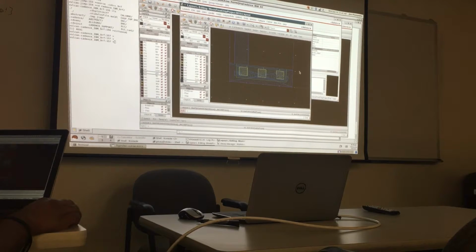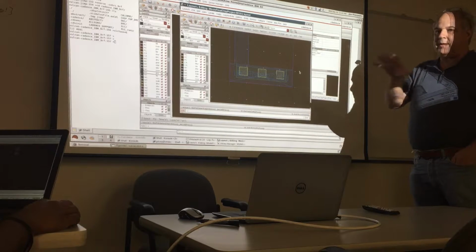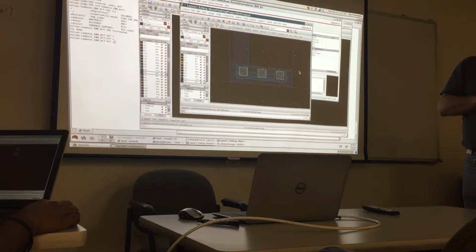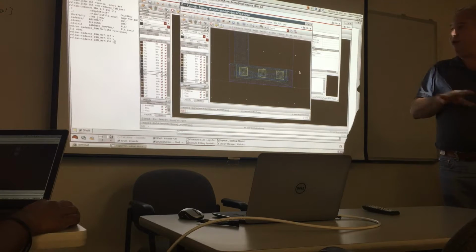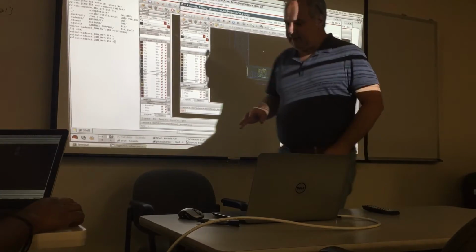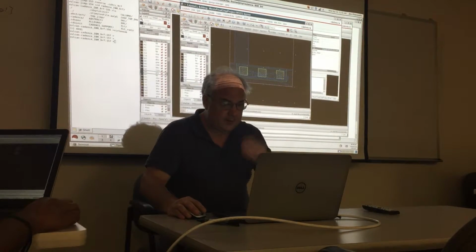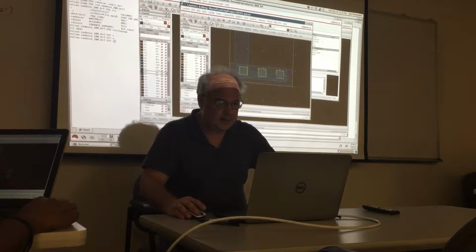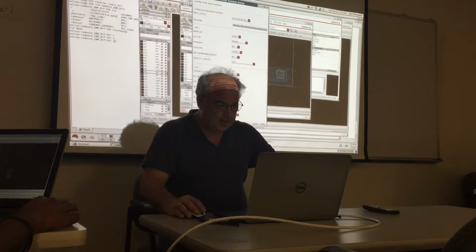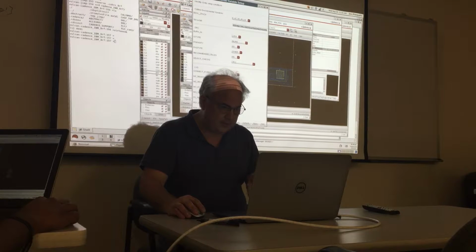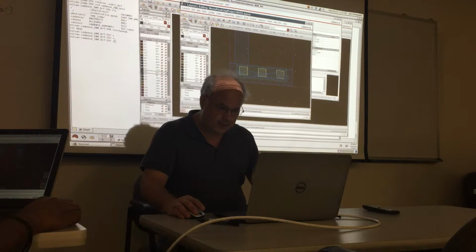Right, yeah, so bring up the inverter from the standard cell library because everyone should do this. I want everyone to get what's called a run set, for at least DRC and LVS. A run set is a set of parameters that you've tuned. So let's see, if I run DRC, this is a PDK menu that allows you to do various things. You just want to hit OK. For standard cell designs, it's already set up properly. So just click OK on it. If we get to chip level, we'll have to change a few things.